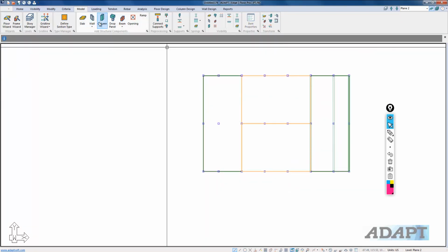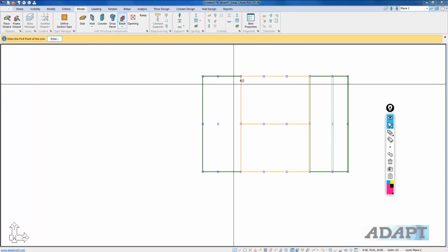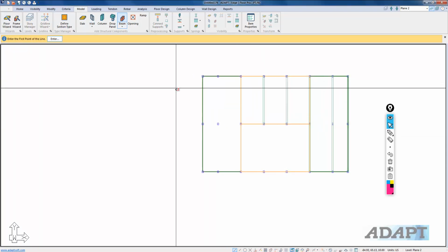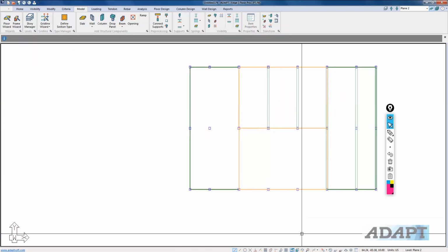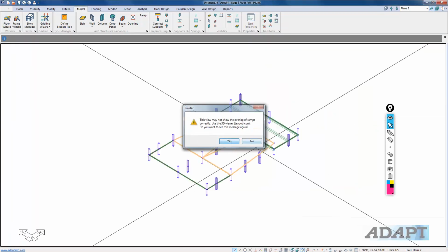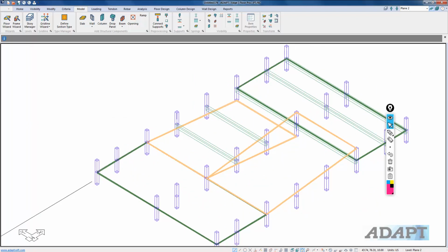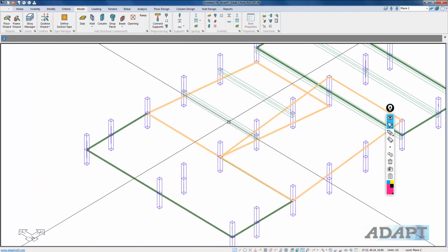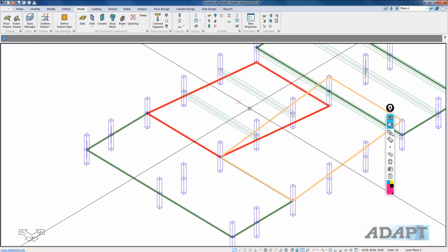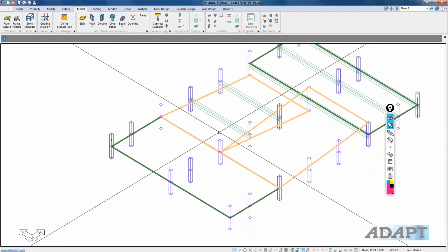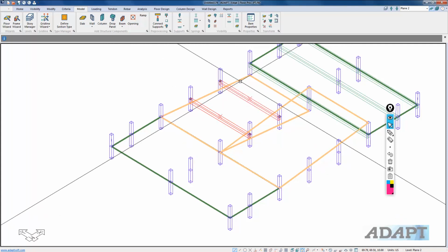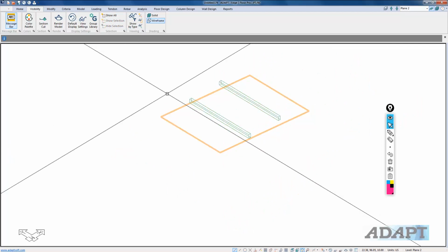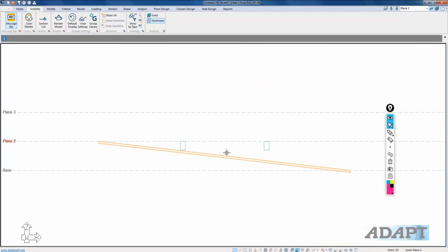Now the beams in the ramp, if we select a beam, let's say we want to model these beams right here. These are actually referenced from level 2, and we want them to be modeled downward. Right now they're at the current plane, so I have to determine what offset I need to drop those beams based on the slope of that ramp. If we isolate the beams in the ramp, I'll just take these and this, go to visibility, show selection, and I'll turn that on its side.